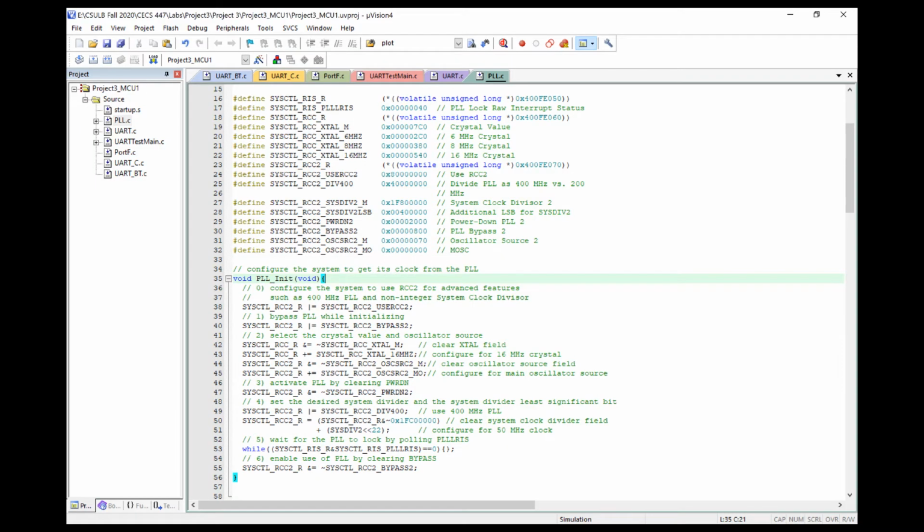First we will get into the first microcontroller's necessary components. The PLL.C file utilizes the onboard crystal to enable a clock and set the bus frequency. This module is required to use timers effectively in the grand scheme of the project. The bus frequency is set to 50 MHz. All timers and interrupts on this project will use this designated frequency.